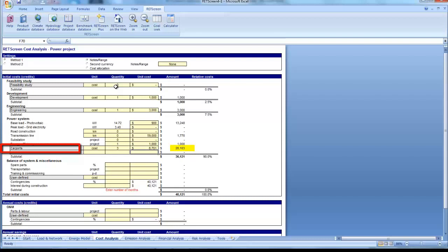This corresponds to an installed cost of $1.18 per peak watt, which is well above the cost of typical fixed support structures alone, but within the current 60 cents to $1.40 per peak watt range with installation time and material. Similar to land-based installation, the solar carport can reduce the installation time since there is no need for roof replacement, anchoring, waterproof ceiling, or structural consideration due to the added load of ballast systems.